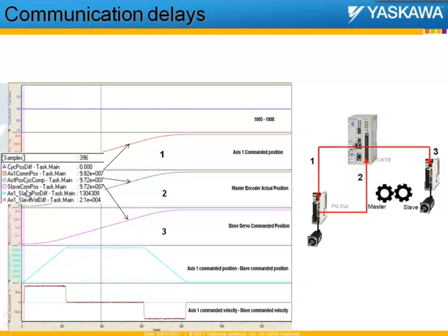You can see here that the axis 1 commanded position was 9.82. The external encoder position came back to be 9.72. So you can see right there that the external encoder is actually lagging behind the commanded position of axis 1. The external encoder is the actual value of axis 1, and you can see that it is itself already lagging. But this data that's coming in is the data that the controller gets, so that data may also be lagging a little bit.